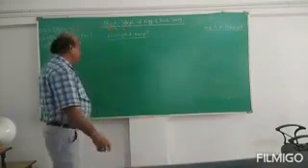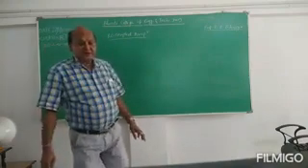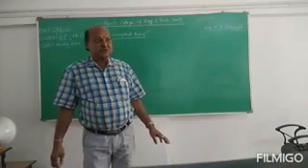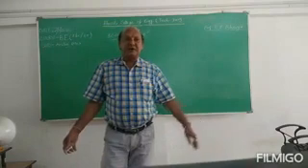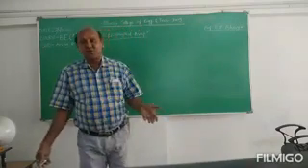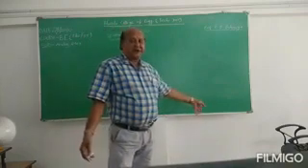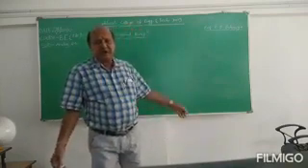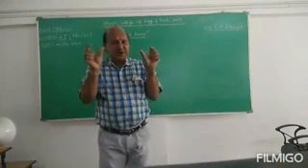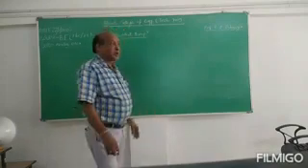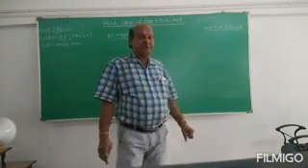This RC coupled amplifier is used in low frequency circuits, where low frequency applications are used from, let us say, 0 Hz to about 100 kHz. For practical purposes, it is used to get a flat response within a particular bandwidth. So we have to find in practical also the response of the RC coupled amplifier.